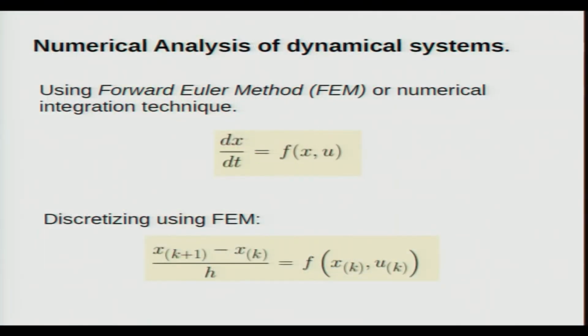Now, there is one interesting point which I wanted to discuss here, which is a very important modeling principle as well, the concept of slow and fast transients. Even before we do this, one of the things you can try at home is to numerically integrate. We tried to get analytical solutions and also did experimentation, but you can also use a computer simulation that uses a numerical method to integrate this response. You can in fact use the Euler method as was discussed in the previous lecture.